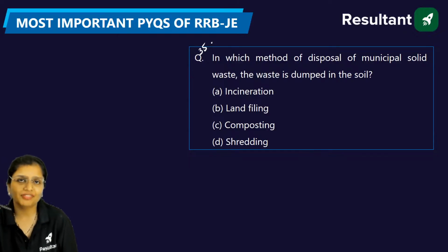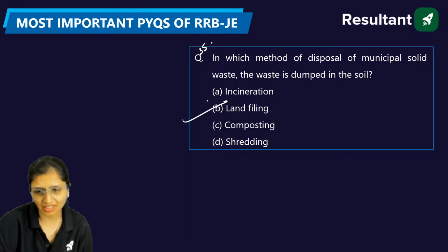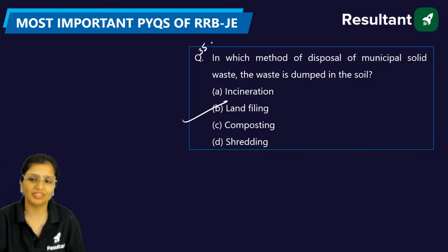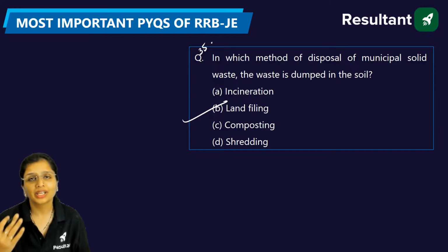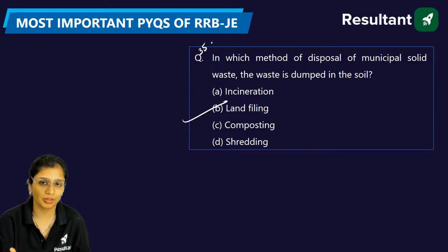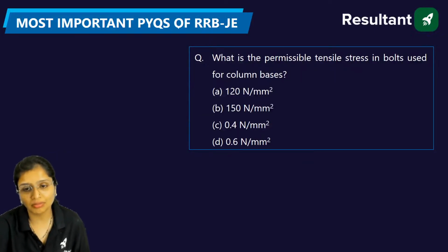Correct. Landfilling method, or you can say sanitary landfilling method, when all the other incineration, high calorific value, composting is done, when large biodegradable matter is there. When you can't do anything, then you will go for landfilling. You will take the solid waste, you will dump it. You go for sanitary landfilling, in which you do compaction and then you dump it properly.